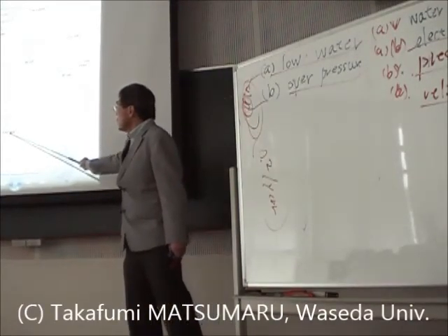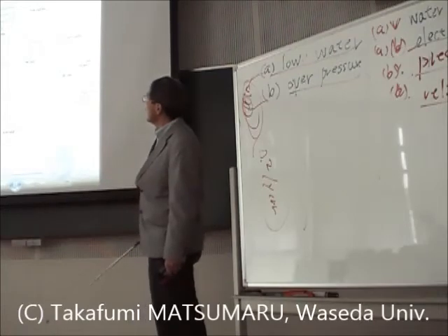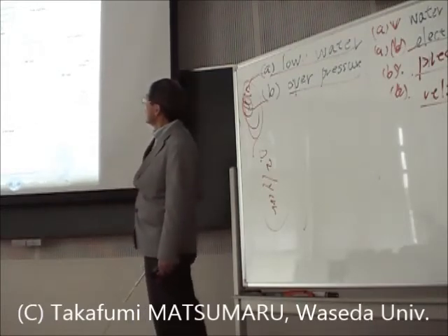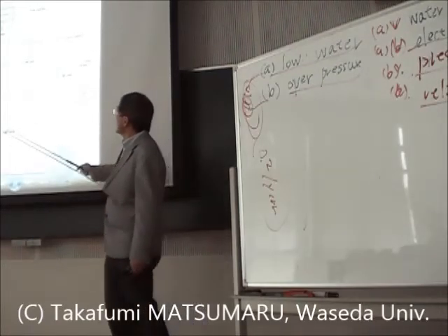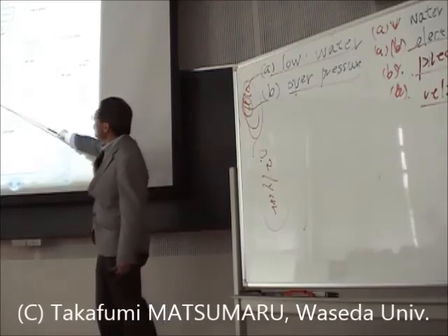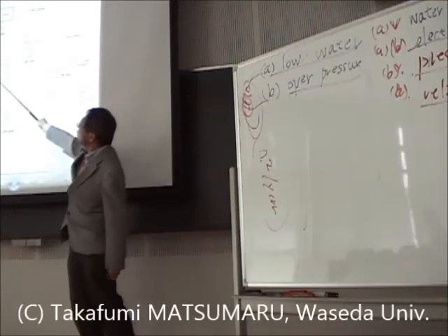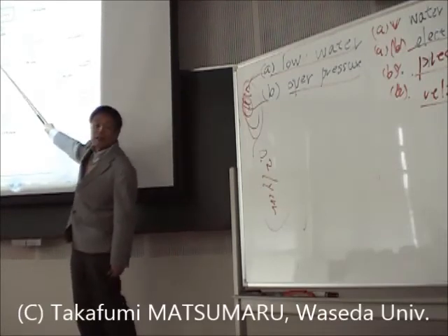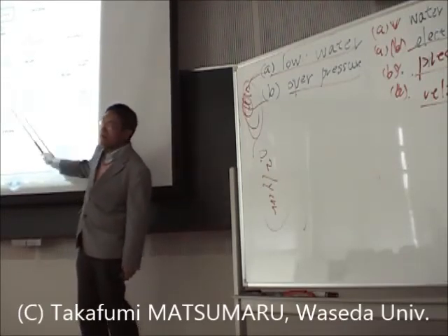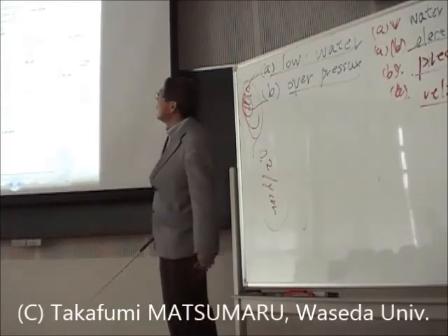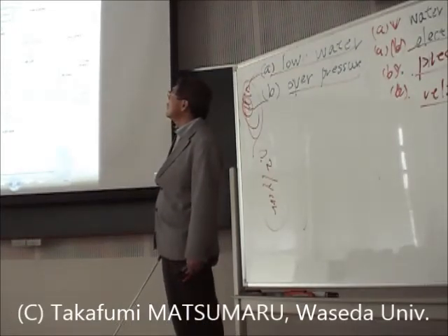And because this is an OR gate, we need to add the frequencies. So to get the frequency for the low water failure, that is 0.1, because this is an OR gate, giving us a frequency of 0.15 per year. Again, for condition B, applying the frequencies to how the overpressure could happen.